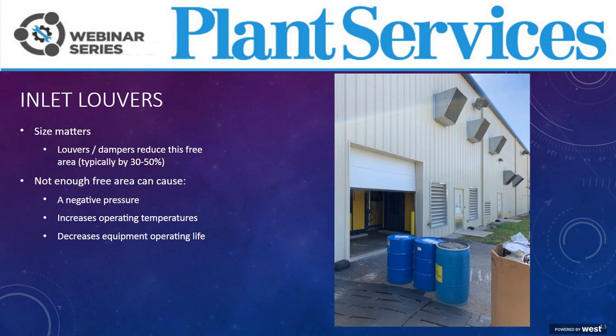So let me give you an example. If you need 30 square feet of free area for your compressor, and you're planning to install a thermostatically controlled inlet louver in that room, you already know that the opening in the wall has to be larger than 30 square feet, but how much? So let's assume you're using a louver that has a free area of 50%. This means that for every square foot of that louver, the free area is 0.5 square foot and the blocked area is 0.5 square foot. So if you need a total of 30 square feet of free area, in our example, you need to double that. So that ends up being 60 square feet.